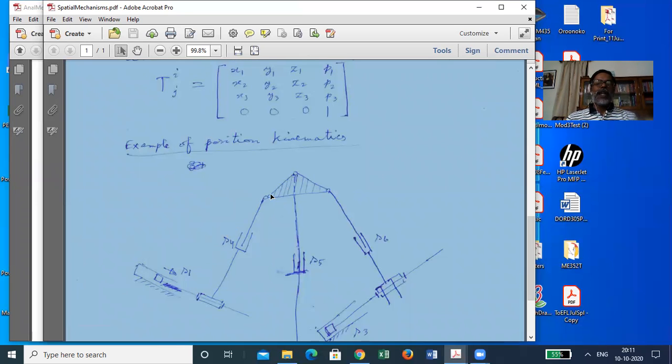And then we can say that whatever is the fixed point from here to this, that vector we get. If we take its components in certain directions, in this direction, in this direction, and then we take the angular position. So from this point, we can describe the length of this, the angle turned by this, and the length of this. And by describing everything in terms of the position and orientation of this platform, what we really do is that three subchains are decoupled.